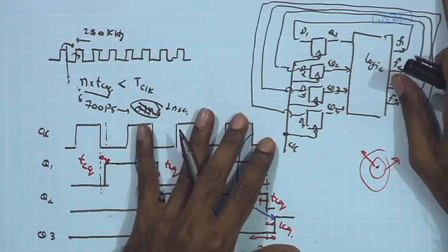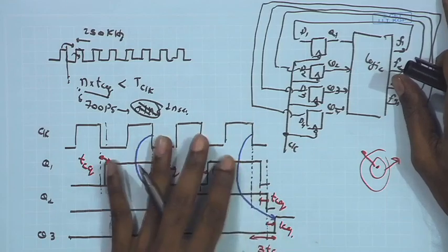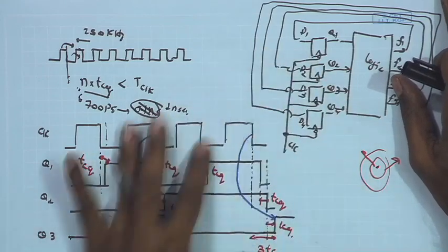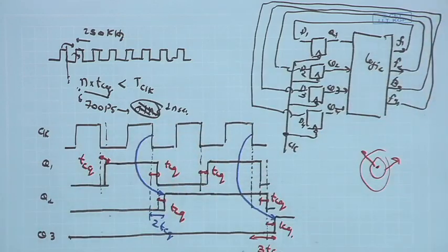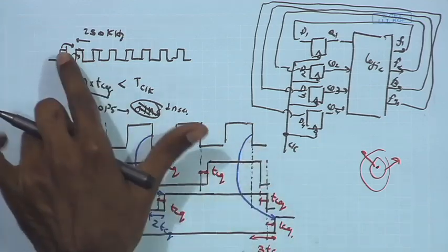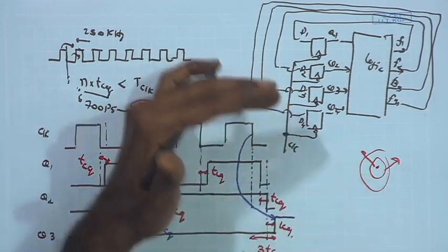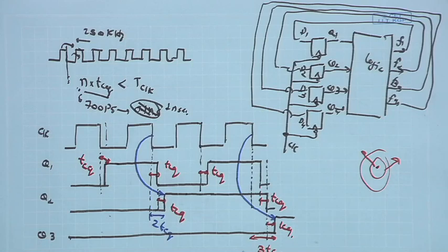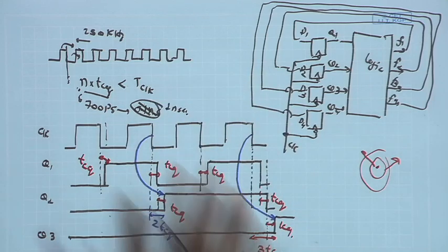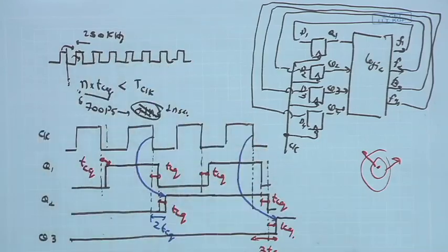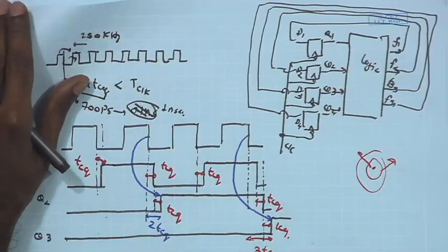Welcome back. Let us resume our discussion on the overall digital control scheme. So far we have discussed the major constituent of the control scheme, which is our ripple counter, and based on that we need to realize our overall control phases or the pulses going into different modules like the comparator, the ramping circuitry, sampling circuitry, offset cancellation circuitry, and so on. So based on the operation of the ripple counter, which is triggered by the main clock, we need to generate the other control phases.